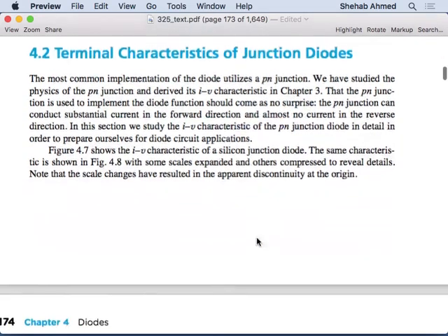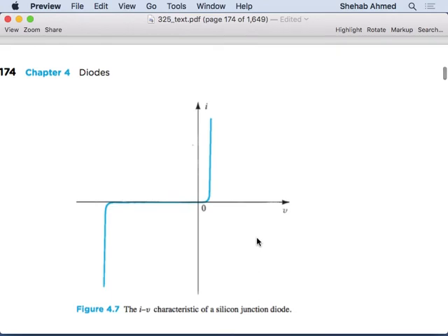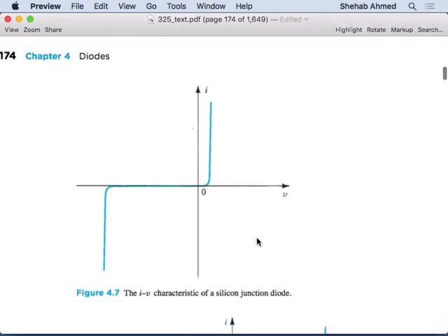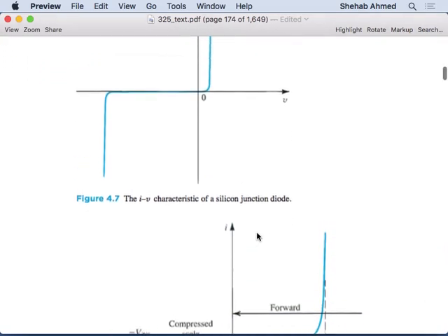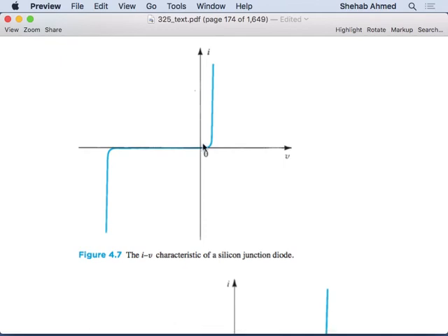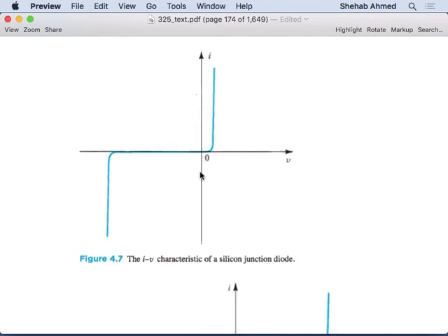Okay, so now let's look at the diode characteristics we talked about a little bit. Here they zoom in on, for example, the origin. Remember what was happening as soon as I start placing a reverse bias voltage. In forward bias, if I have a small forward bias voltage, it means I still have a high voltage barrier to diffusion. Only when I'm able to decrease that voltage barrier to diffusion am I going to start current conduction. That's in the forward condition.